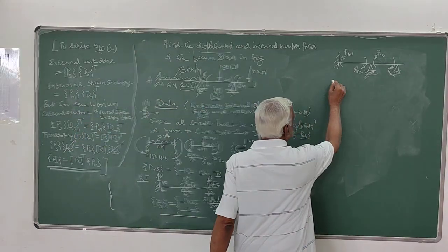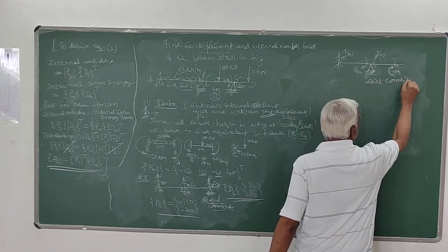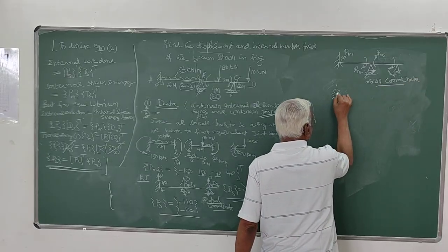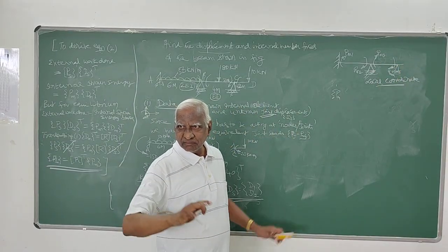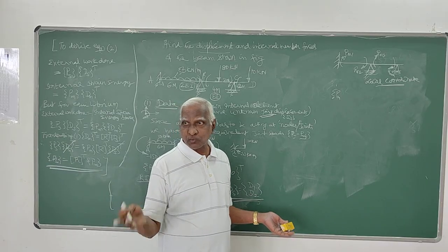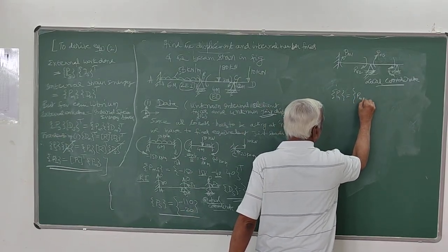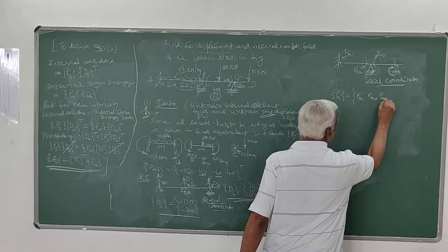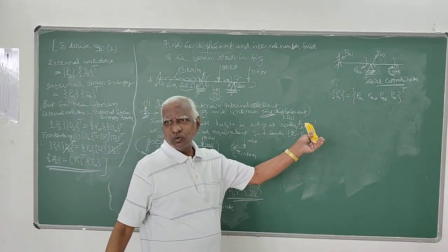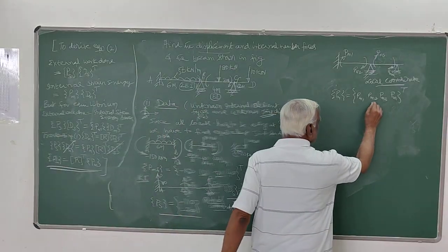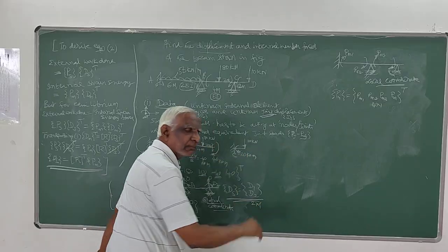Correct? So the unknowns to be determined here, this is local coordinate. So your local coordinates 1, 2, 3, 4. 4 coordinates locally, for which we have to solve the internal member end forces. Only moments I will select, they are the independent ones. So PM will be equal to PM1, PM2, PM3, PM4 transpose. It's actually a column vector, written in a row with a transpose notation. This is 4 by 1 actually. So this is 2 by 1.